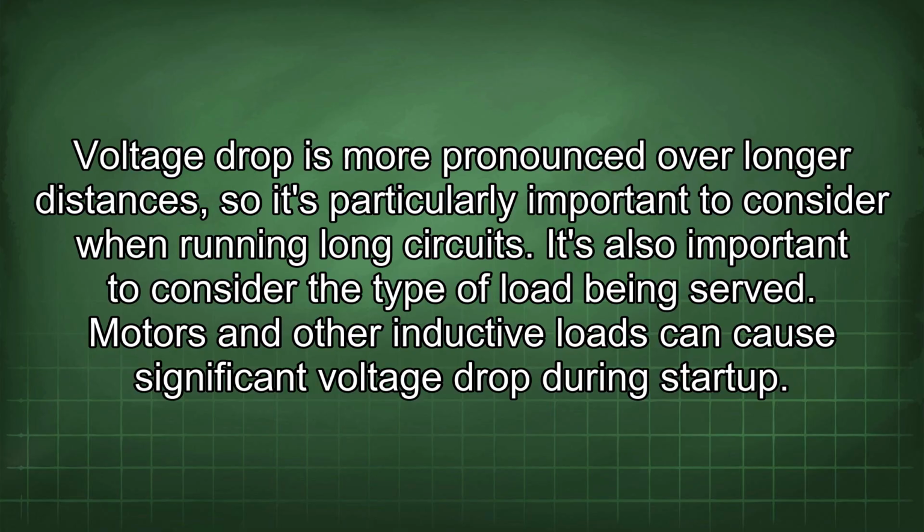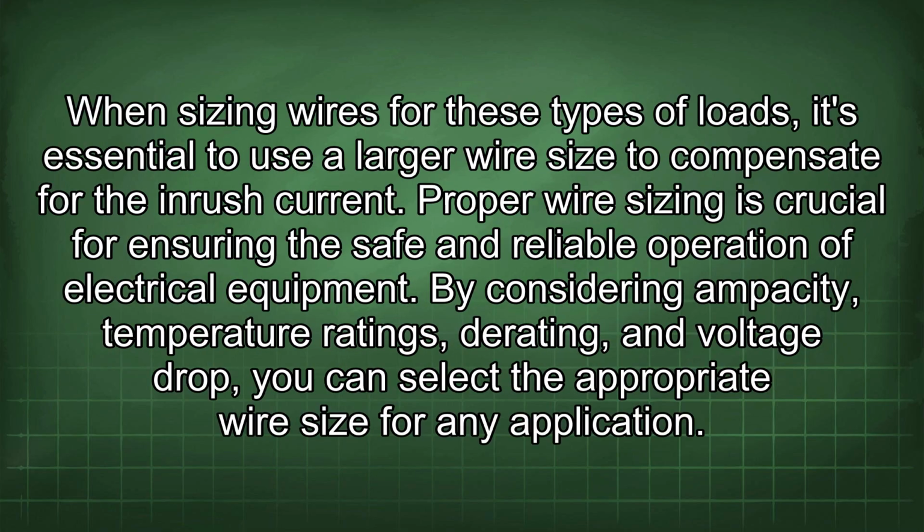It's also important to consider the type of load being served. Motors and other inductive loads can cause significant voltage drop during startup. When sizing wires for these types of loads, it's essential to use a larger wire size to compensate for the inrush current. Proper wire sizing is crucial for ensuring the safe and reliable operation of electrical equipment.